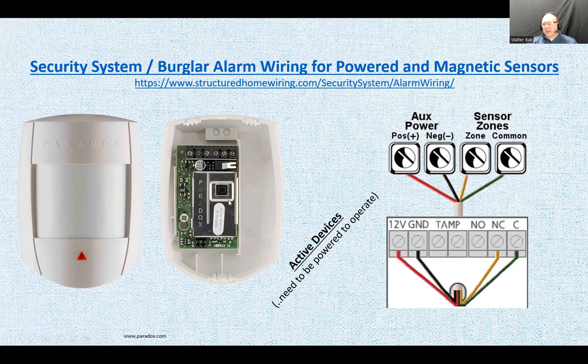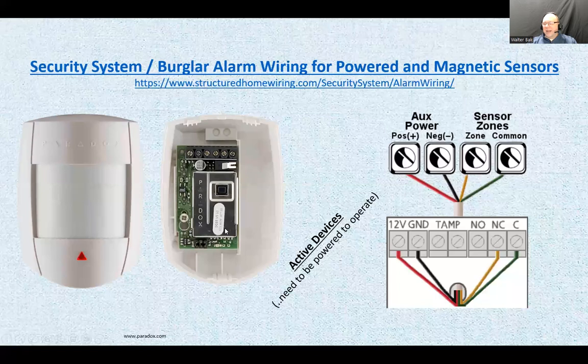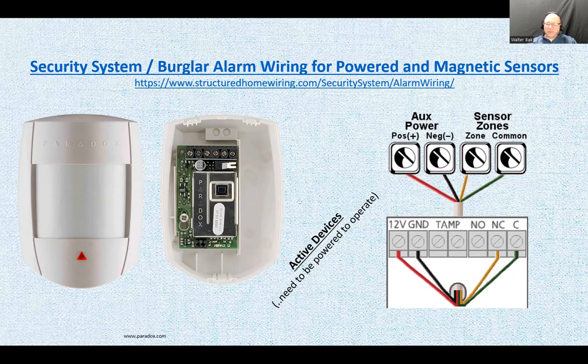This particular one works on infrared. It looks for the infrared signature of a person, usually, and if it sees a movement of that, it is going to trigger into a condition. That's why these motion sensors should not be pointing at a door where there may be a draft, or a window that is too cold in the winter and lets too much warmth in during the summer. They should also not be installed in front of fireplaces, wood stoves, heaters, and whatnot. A heater can trigger the alarm. And they should not be pointing at each other because it's infrared. Some of them employ microwave technology, and some laser beams and whatnot.